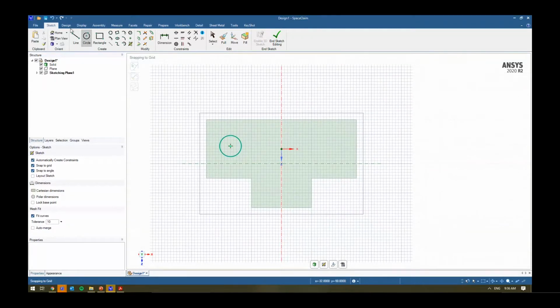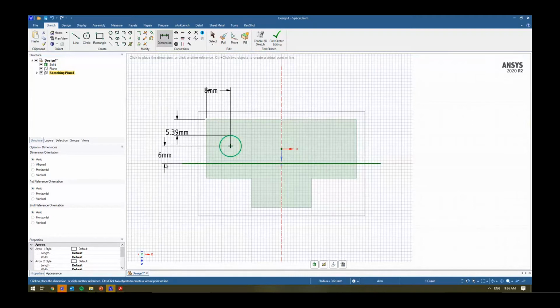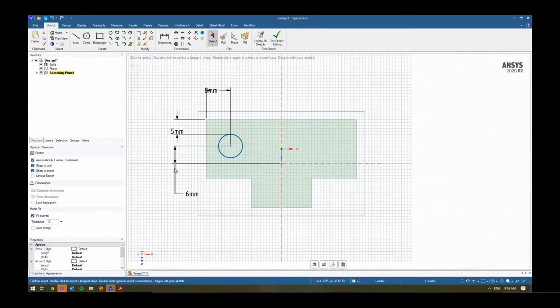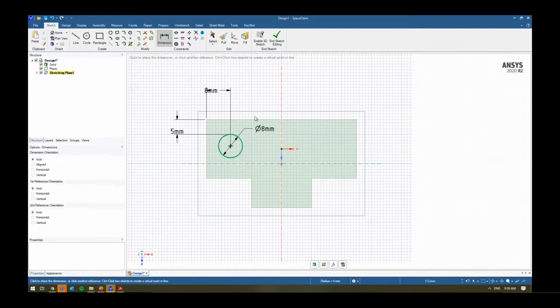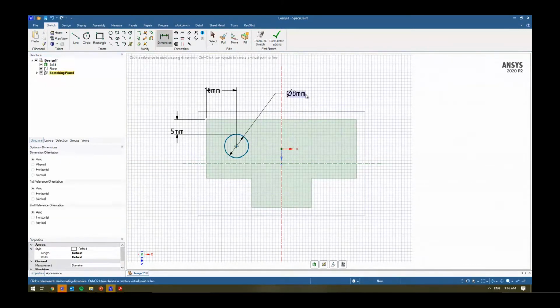So I'll use a little bit of dimensioning in this particular case. Let's just say I create my circle. I can go to my dimension and dimension what the parameters here might be between these components, right? So let's do that. Then I can select it. Let's just say I want to make it 5 instead. So let's delete that parameter. And I want to take the radius there, the diameter. I can make that 10. I can go in and say make that 5 as well.